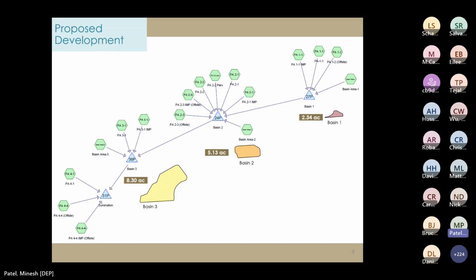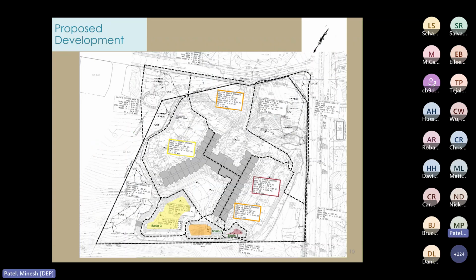So here's the drainage area map for the post-construction condition. This shows the contributory drainage to each small-scale bioretention basin is less than the allowed maximum of 2.5 acres, which appears to demonstrate compliance with 7:8-5.3b. But we have to dig a little further to evaluate how individually versus connected the basins performed when it comes to the water quality, the 2, the 10, and the 100-year design storms.